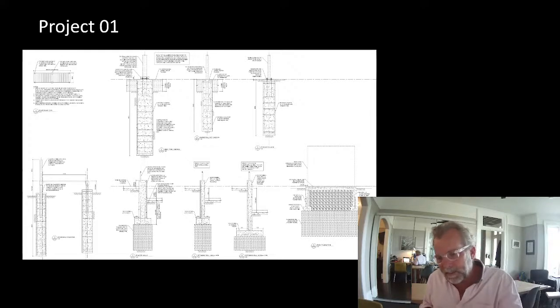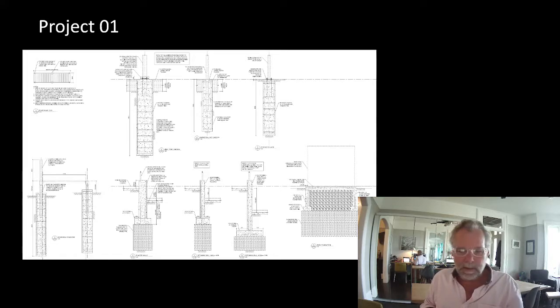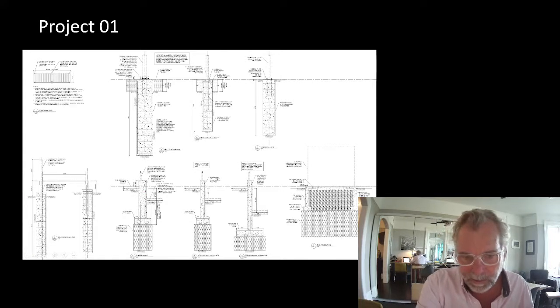That said, in a condition like this, the amount of water that goes through is not significant. So we get a small amount of water through. It just works its way down through the voids in the clear crushed stone, and we will not have heave.